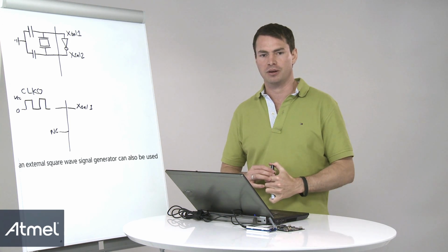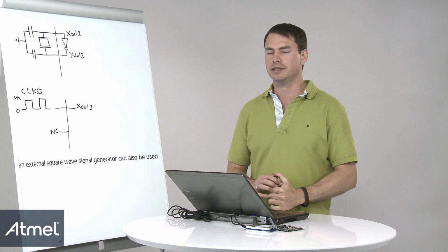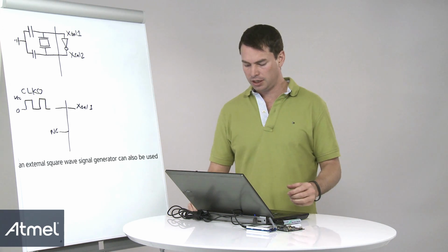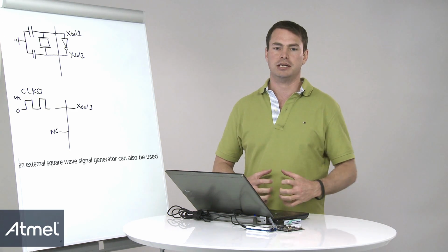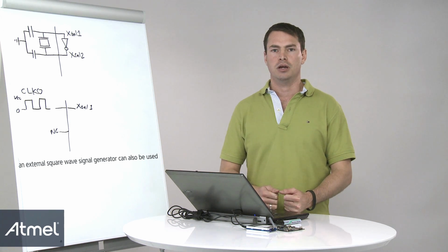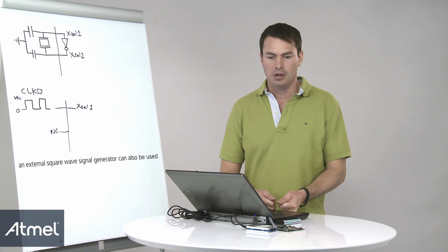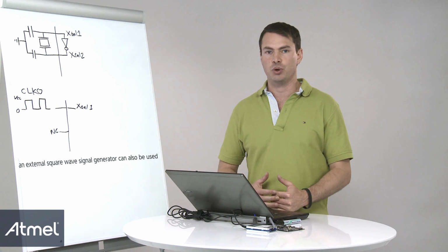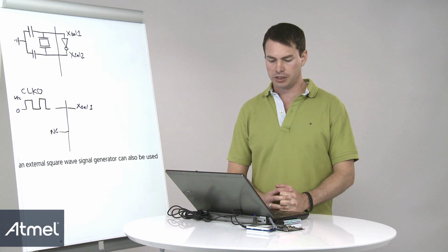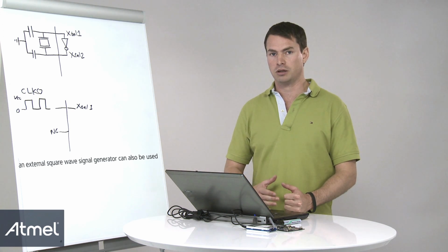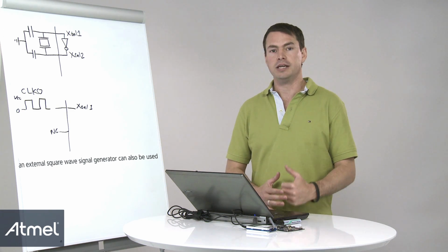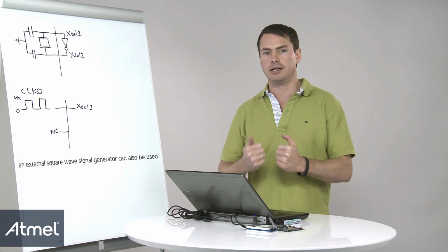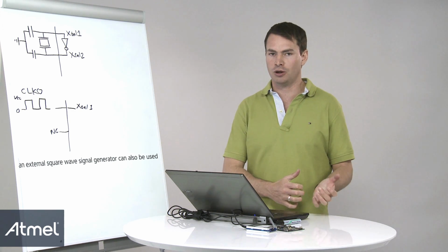So let's talk about, as concluding remarks, also why this is impossible to do on an XMEGA. Well, the difference with the XMEGA is that the default clock source is an internal 2 megahertz RC oscillator, and that the processor always starts up on this 2 megahertz internal RC oscillator, and in order to change the clock source, that is done by software as opposed to fuses, and so the processor actually has to be executing code in order to change the clock source.